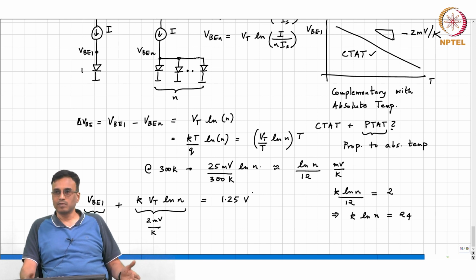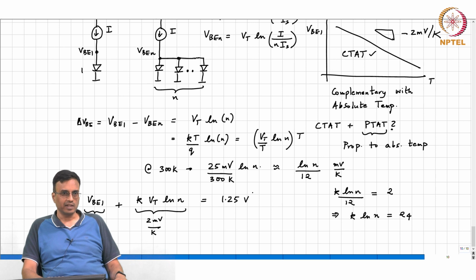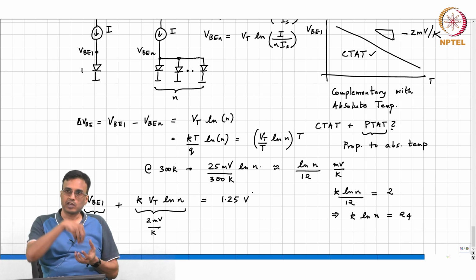So, once people figured that out, what would they do? You either make an alloy which combines metals in the right proportion, so that the net temperature coefficient is 0. That alloy is called INVAR, which stands for invariant. Or otherwise, they make a hollow tube of one metal and inside they pour mercury.